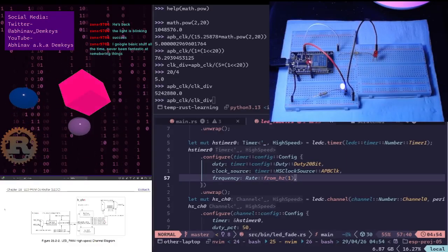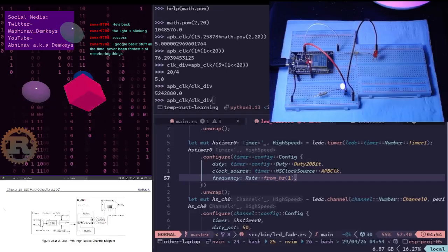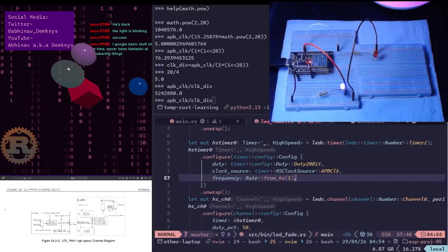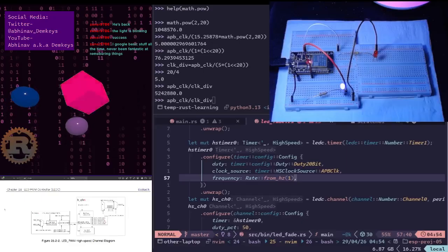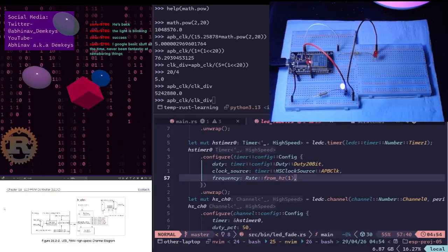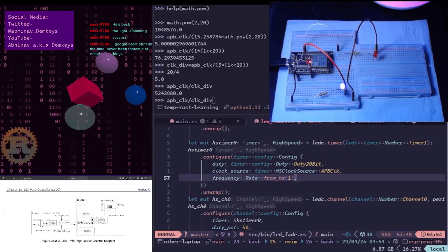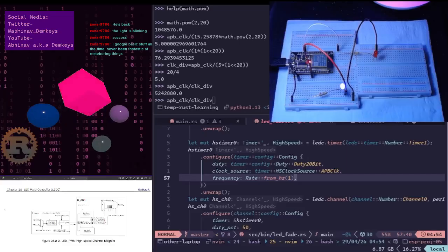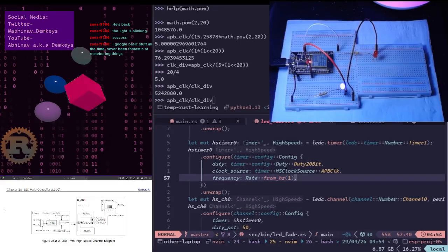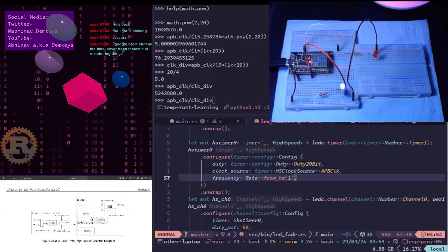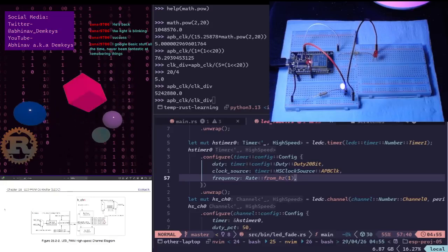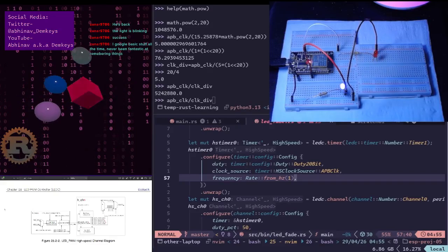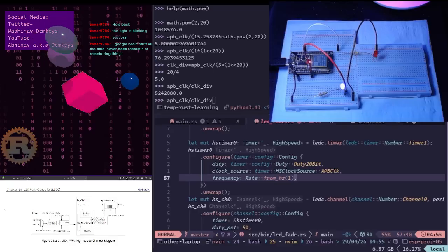It's still running on the APB clock signal, but it's only incrementing whenever the divider tells it to increment. So technically, then yeah, it is running off of the divider only, unless it's doing something else later on with that APB clock 80 megahertz signal. Unless that's the case, yeah.